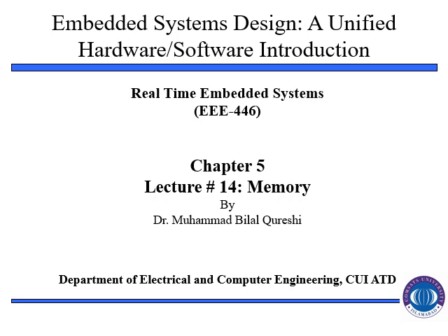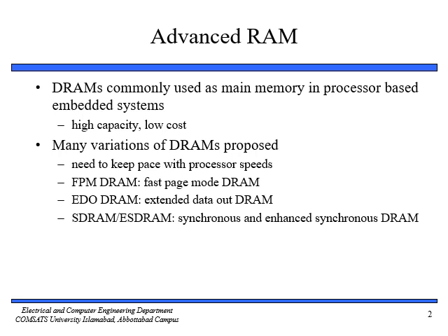So let's start. Earlier we described DRAM, that is dynamic random access memory, as a type of storage device that uses a single transistor-capacitor pair to store a bit. Because of such architecture, it results in high capacity and low cost. DRAMs are commonly used as main memory in